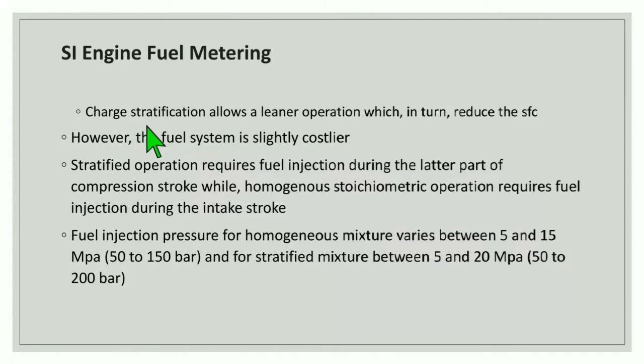Charge stratification allows a linear operation, which in turn reduces the SFC. However, the fuel system is slightly costlier. Stratified operation requires fuel injection during the latter part of the compression stroke, while homogeneous stoichiometric operation requires fuel injection during the intake stroke. Fuel injection pressure for homogeneous mixture varies between 5 and 15 MPa, that means 50 to 150 bar, and for stratified mixture between 5 and 20 MPa, that means 50 to 200 bar.